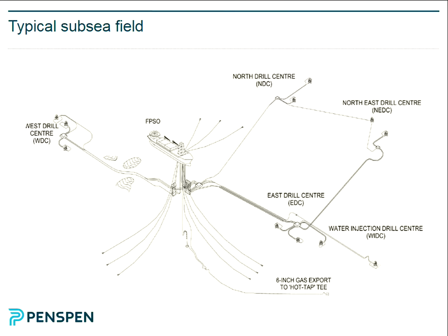And it's also possible to even boost the reservoir. So in fact, if you don't do that, you might find the whole seabed will start to settle and move down, which is what happened on the Ekofisk field, which is in the Norwegian sector. The whole field started to move down to a point where the spider deck of the platform actually ended up being close to the water, and they had to jack up the platform at vast costs. So injecting water is a critical aspect of hydrocarbon production, but also it can potentially avoid this settlement as well.